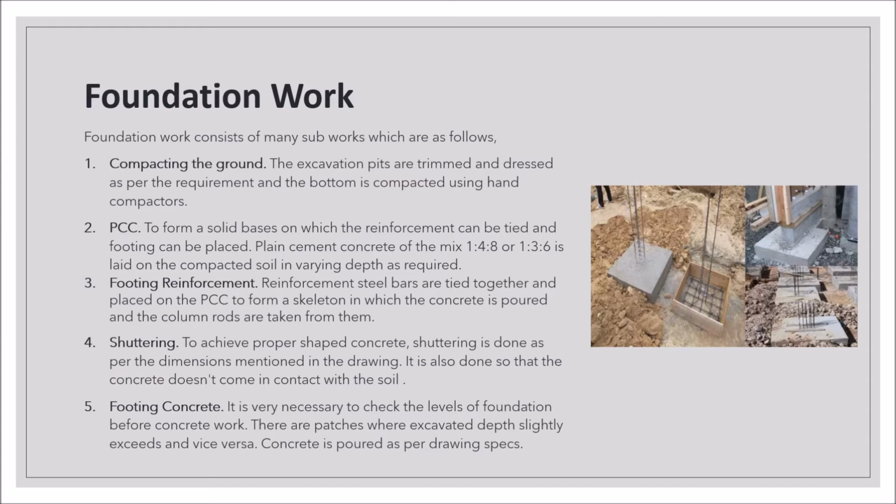Plain cement concrete of mix 1/4/8 or 1/3/6 is laid on the compacted soil in varying depth as required.